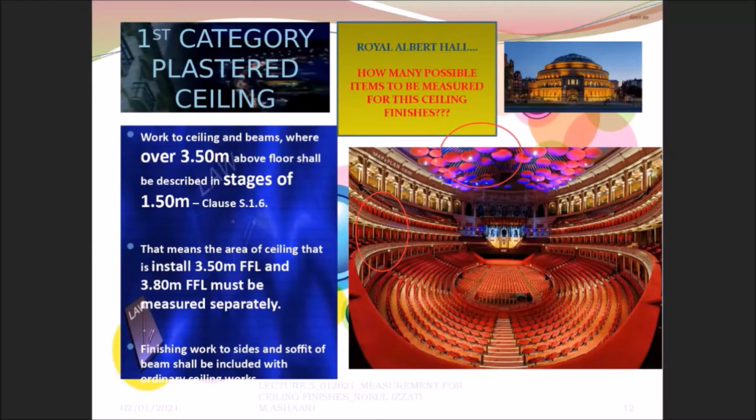If I mention at the center 6 meter, can you measure it with another room having 3 meter FFL? If you have a room with a floor level of 6 meter and another one with 3 meter FFL, can you measure together under one item? Same specification, same type of ceiling. Can you measure together?